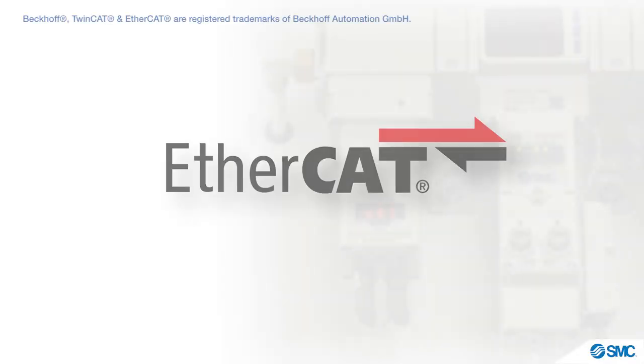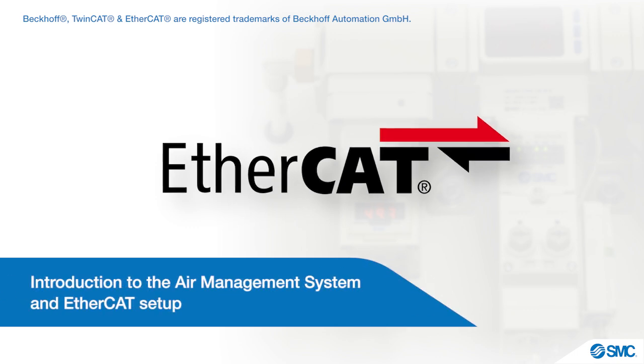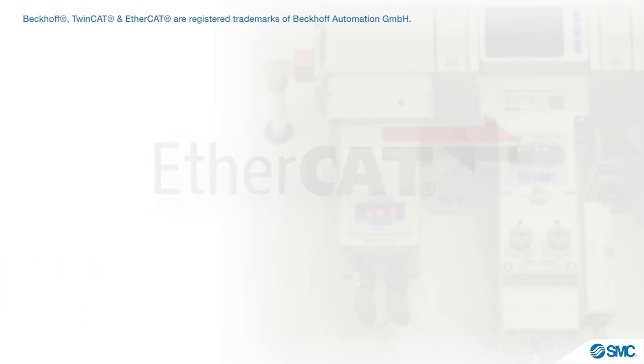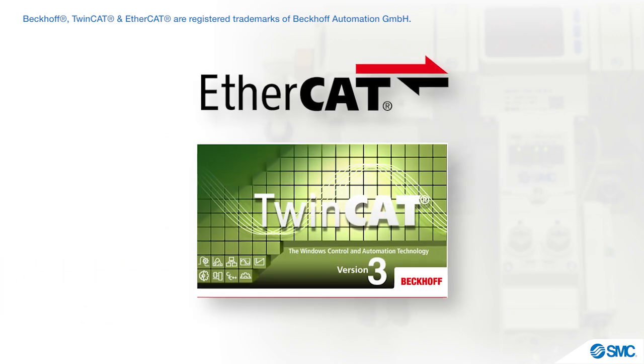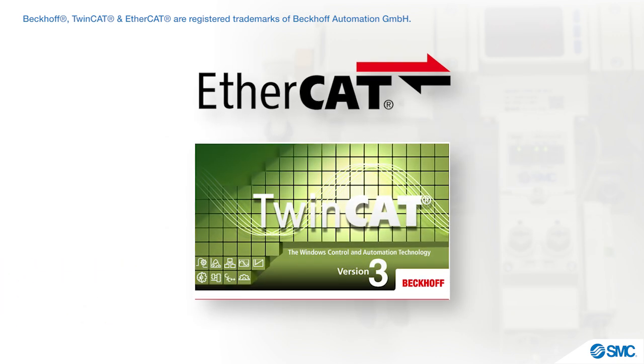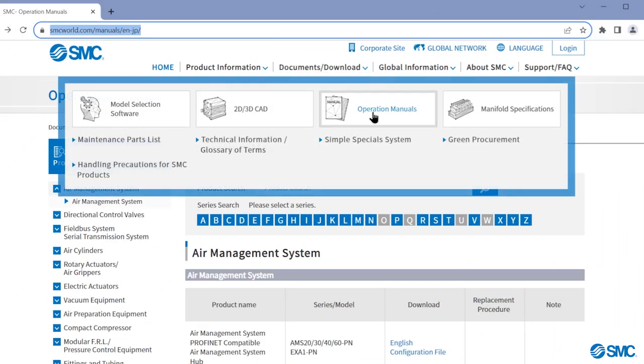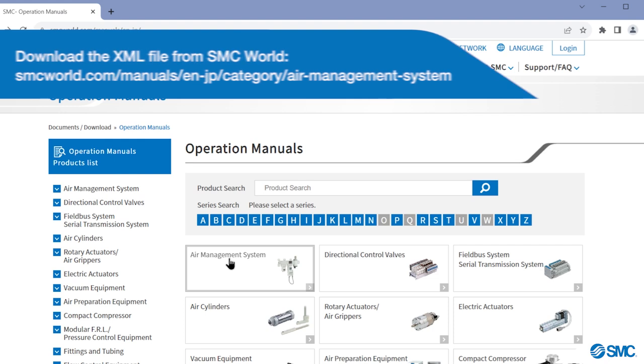This video introduces the air management system and EtherCAT setup. For this video tutorial, we will be setting up the EXA1 system with Beckhoff TwinCAT 3.1. We first need to download the XML file from the SMC World website.